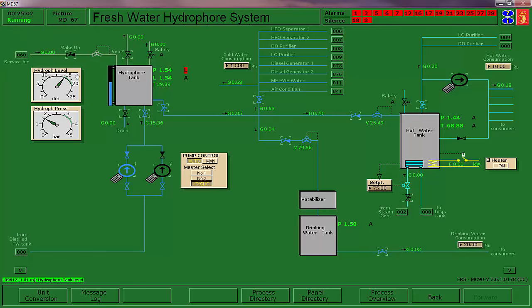That's a reminder. We'll go ahead and put on our cushion air. You'll see your pressure will come up pretty fast now because I'm pumping water in plus supplying air pressure. And I'll usually just give it enough cushion air to clear the alarm. Let me go ahead and shut that off. I'll go ahead and put my hot water circ pump on at this time and my electric heater.